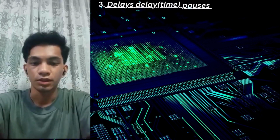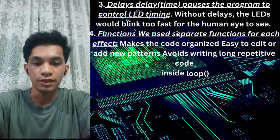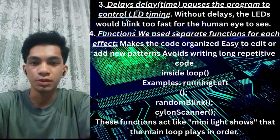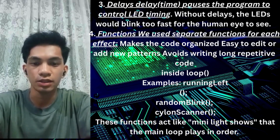Three, delays. The delay function pauses the program to control LED timing. Without delays, the LEDs would blink too fast for the human eye to see. Four, functions. We use separate functions for each effect, which makes the code organized and easy to edit or add new patterns. This avoids writing long, repetitive code inside the loop.